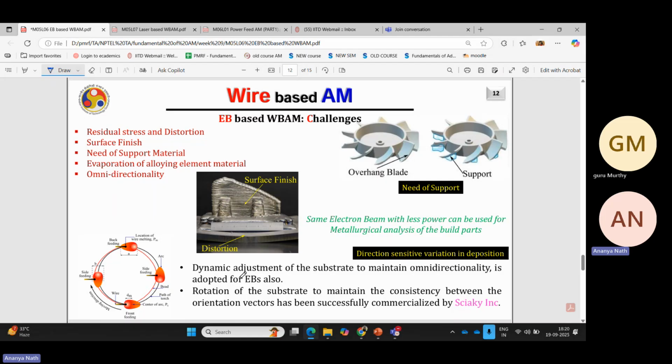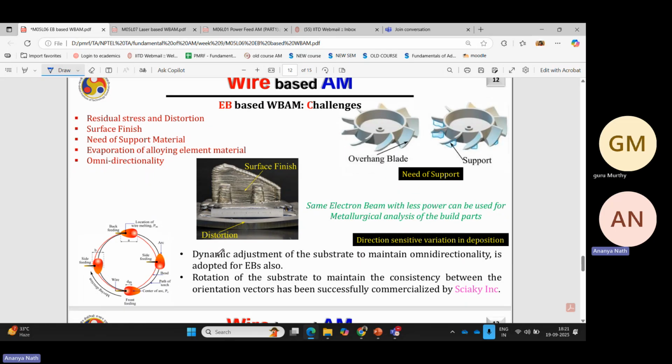As we are doing it in a vacuum chamber, it's already a very costly process because we need to install the turbomolecular pump, and if you are printing a very big volume, then you need a very big chamber with a very high energy pump, which will enhance the cost. Also, it's very difficult to create vacuum in a bigger chamber. So size is one thing which is restricting, or a drawback we can take it.